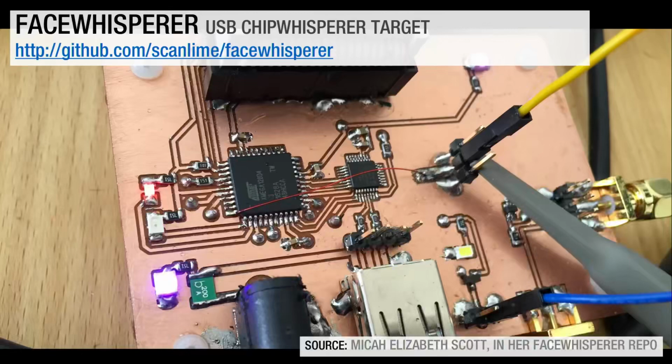And this particular board contains a microcontroller, which happens to be the same one that is on a ChipWhisperer, and a USB host chip, which happens to be the same one that is on a Facedancer, and then some clock buffering hardware. And all that it does is, with very precise timing, synchronize itself up to a particular point in the tablet microcontroller's program execution, and then send it some USB packets and simultaneously trigger the ChipWhisperer to start executing glitches.